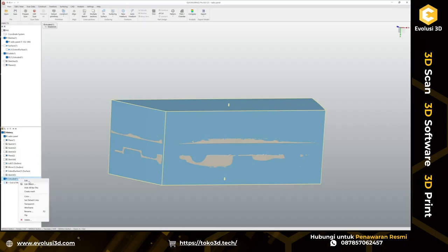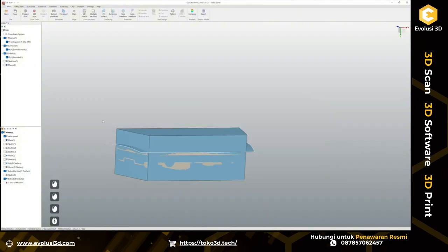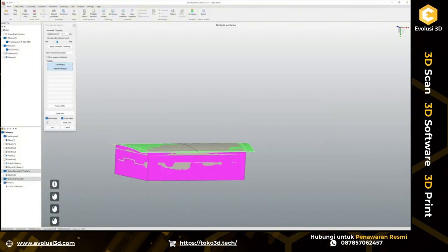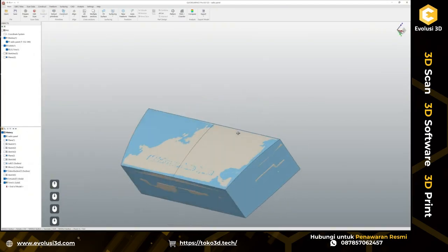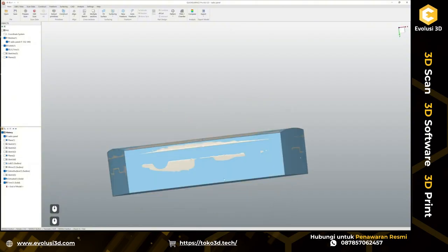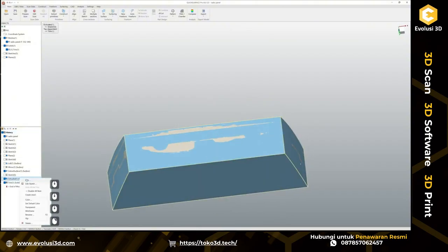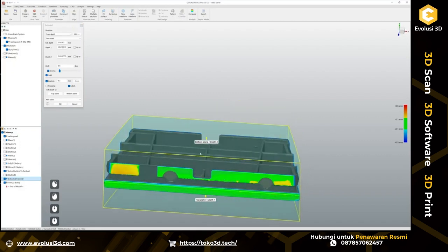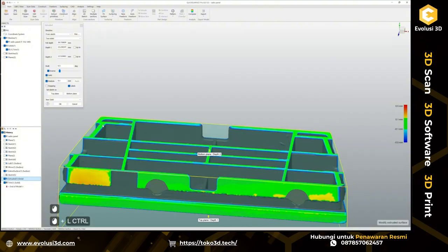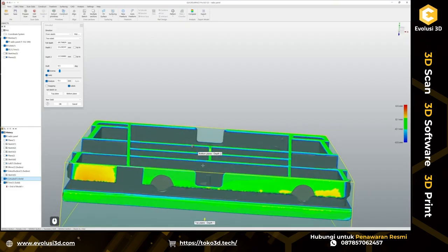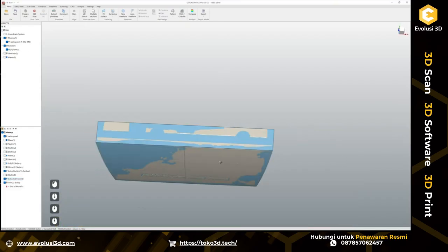Okay, but I wanted this to be a surface probably. Or actually, maybe not. I can simply trim this with previously created surface. Oops. Like this. And I have the main body mostly created. Let's just change the extrusion distance to the bottom side. Okay, like this.